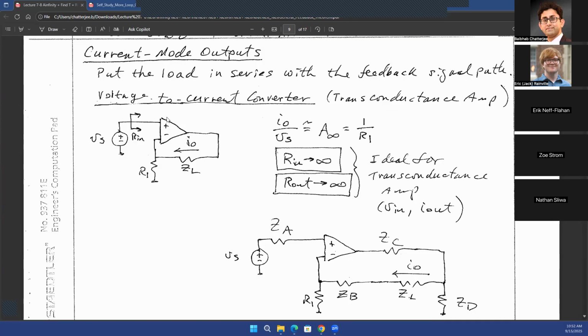So from Ohm's law, what is resistance? Resistance is the ratio of voltage to current, right? Now, let's say you're connecting a test voltage source at the output, Vx or V test. You are interested in how much current actually goes through your output from that voltage source. That is your output impedance. So the voltage at your output node divided by the current at your output node is your output resistance, right? So what is the voltage at your output node? It's over here, because this is the path, and this is what you're defining as your output current for the system, right?